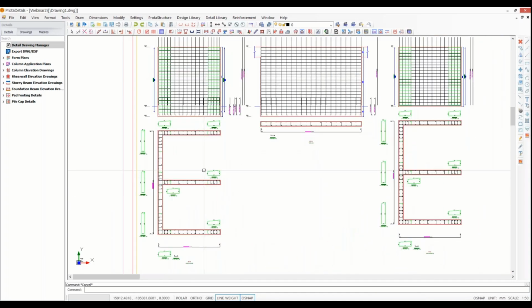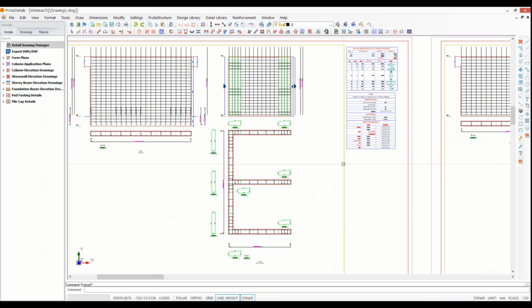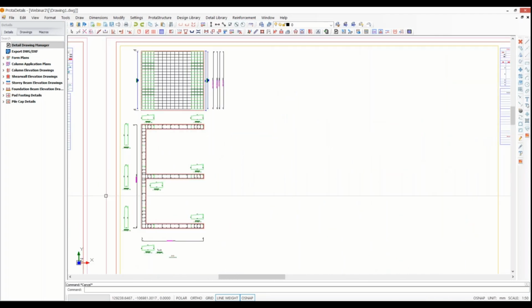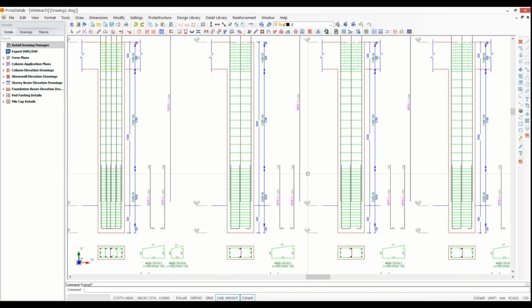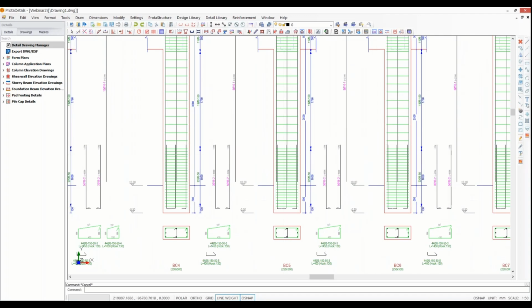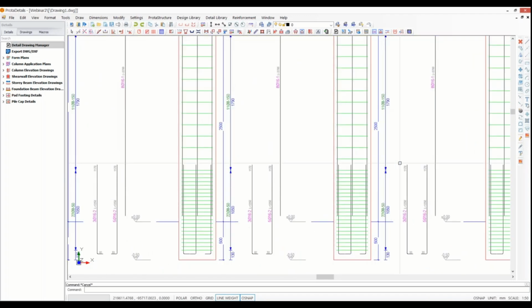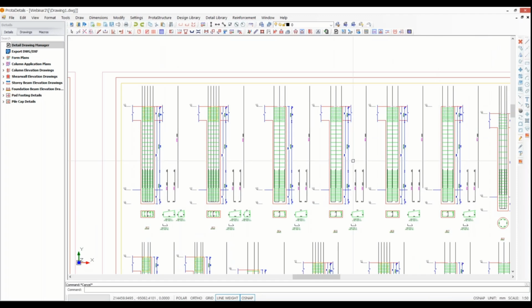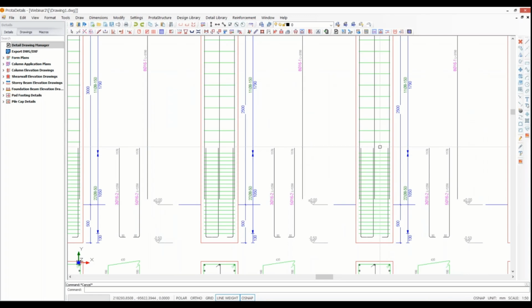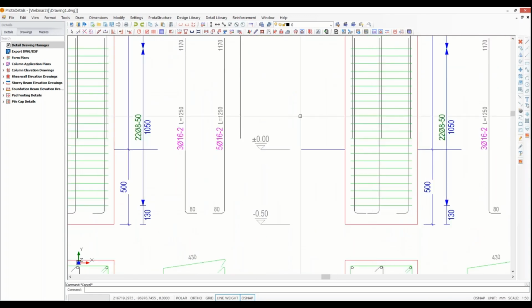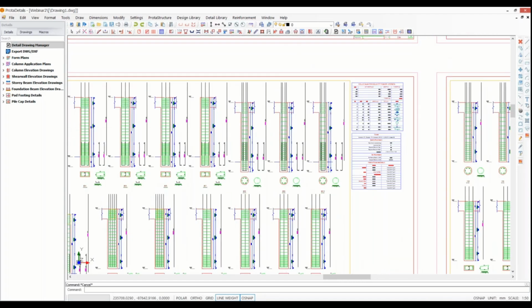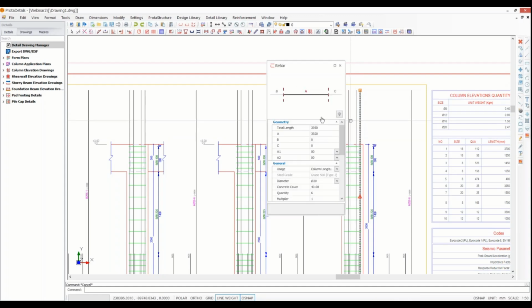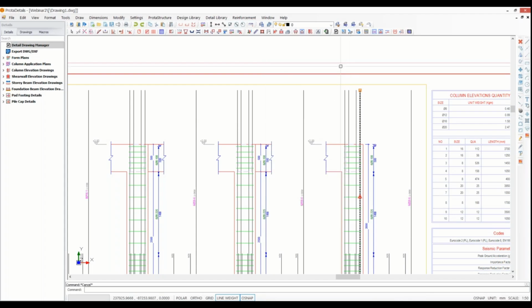You can see our shear wall details, which are prepared precisely. Also column details. You can see the confinement zone, because we have selected high ductile class structural system. So that's why you can see these confinement zones. By the way, if you want, you can also play with these column rebars as you wish. You can change the lengths. It's up to you.